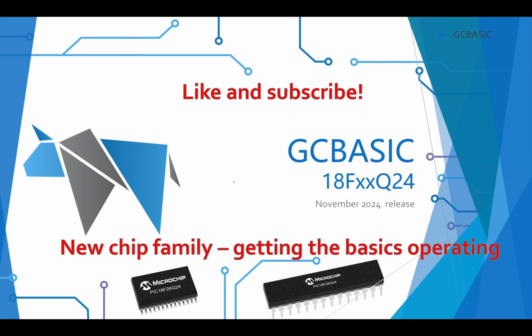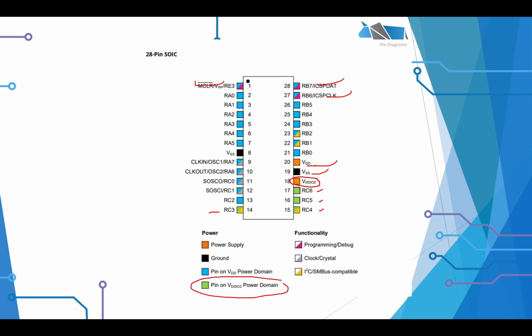So you have to put a VDD supply on pin 20 and a VDD domain, that could be 3 volts, 5 volts, whatever voltage you select. You need to put it on it, otherwise the chip won't work. The chip currently has no supply voltage into the VDDIO2 power domain. It has it on the main power domain, but not in this particular one. Hence, the chip is sitting there stationary.